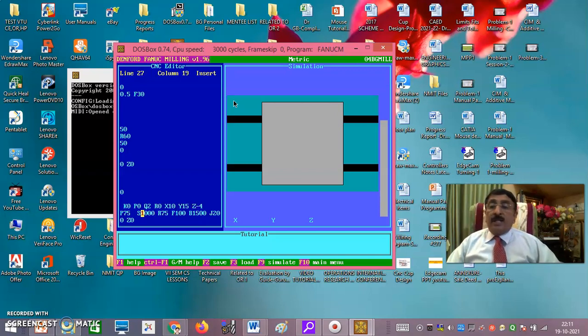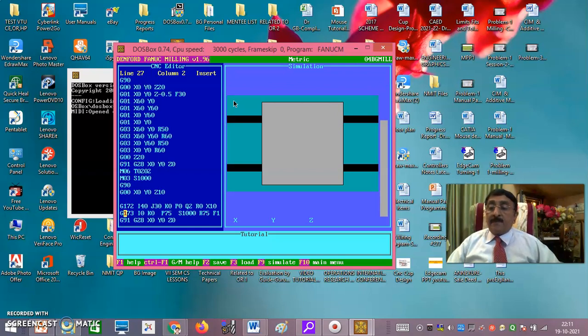Okay. Now as you see here, I0, K0 is, since it is a roughing cycle, there is no base allowance and side allowance also 0. P75 means 25% overlap between successive passes, so that the finish becomes better. If I make P50, 50% overlap. P25 means 75% overlap. The finish will be much better. Anyway, I have given 25% overlap.